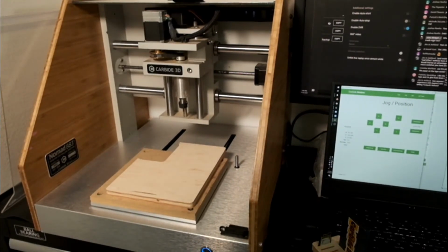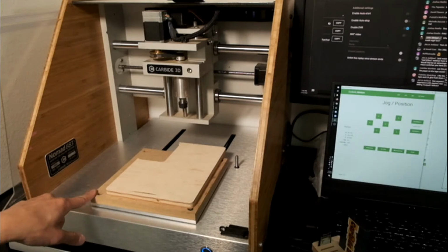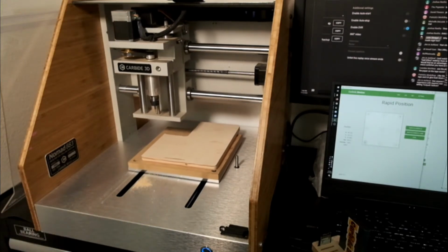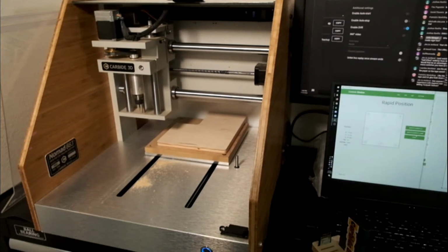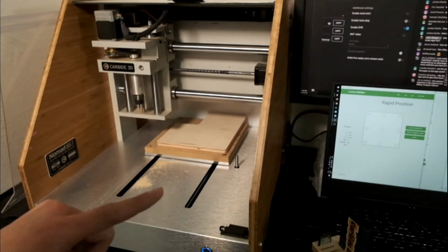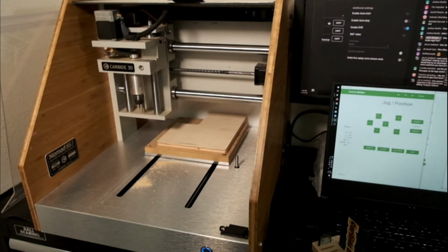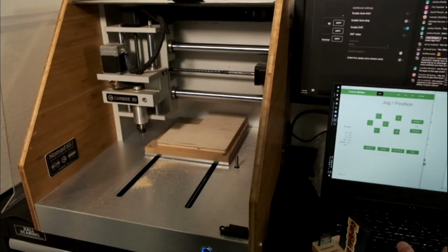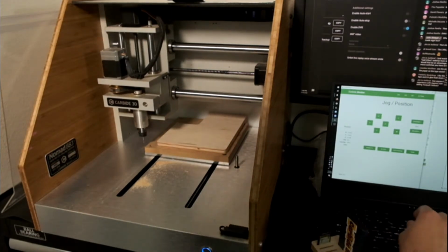So I'm going to rapid position to probably this corner. So southwest. And then I don't trust my Z offset since I haven't run this machine in a while. So I'm going to switch to fast jogging and use the comma key to bring us down. 3 to switch to 1 millimeter increments.